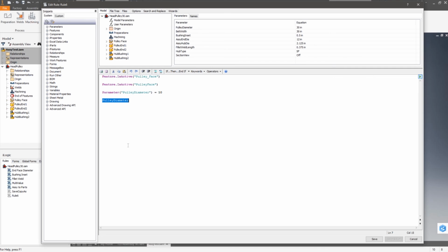What I mean by that is if you create a subassembly that has a configuration that you desire, and now you have another subassembly that is similar but slightly different, sure, do a pack and go on that if you want to. If the file paths are complex and you don't want to track everything down, you can just do a save of that assembly and it's going to grab it. You can do the same thing with a drawing because it has file references as well.